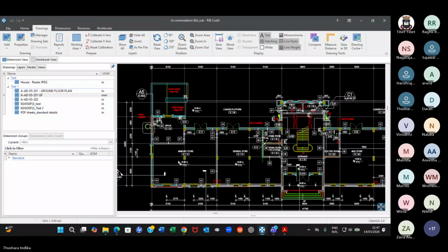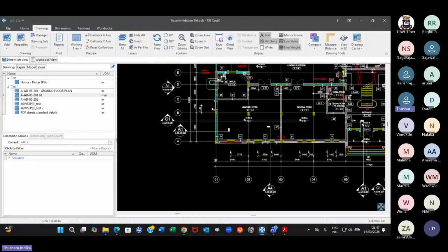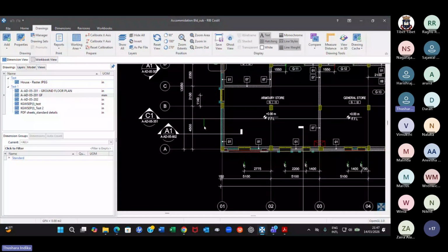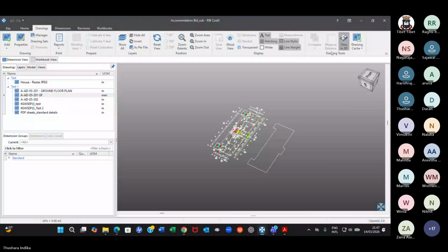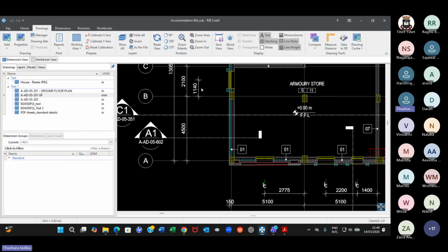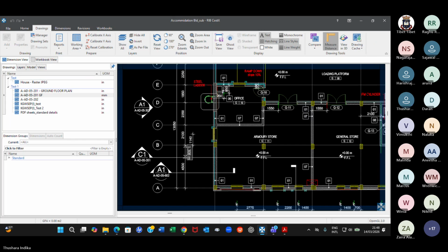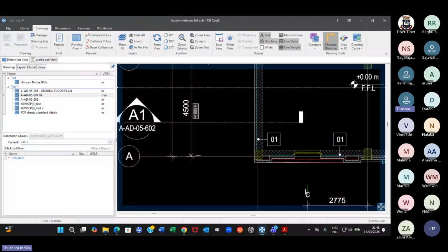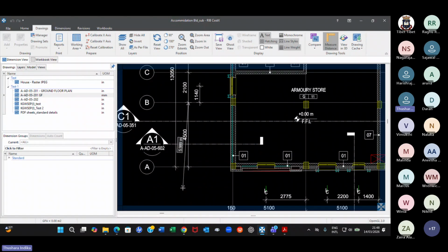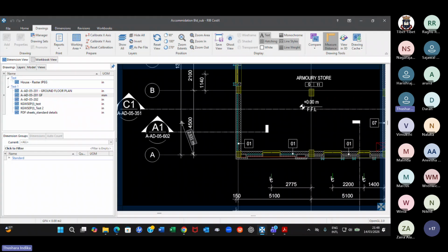Then you double check. How do you double check? Let us measure y-axis, any dimension. Measure distance, sorry. Reset view. Click on this 3D. You don't need that. Okay, I'll show you the 3D thing later. Now you measure. Measure the distance here from here to here. Okay. Here to here, 4.5. Here also 4.5.